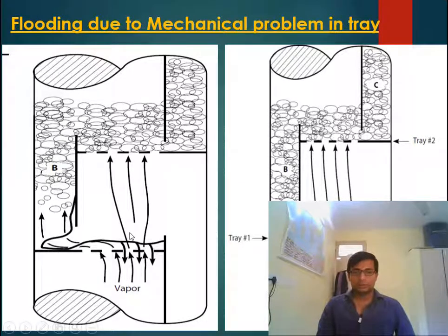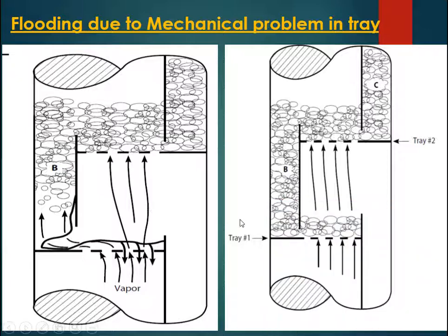Now if sufficient vapor is flowing through this tray spacing also, then liquid will not dump, rather liquid will back up on all the trays, and this may lead to flooding. And if all of the vapor is going through this downcomer, then it may lead to dumping. Okay, now similarly, suppose I am providing very little downcomer clearance, what happens in that case?